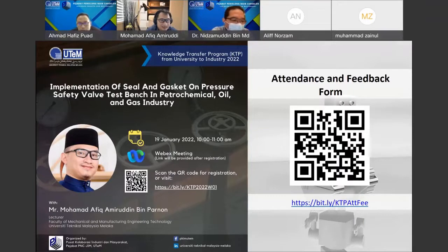Yes. The backup ring, because they have a backup ring, and then the O-ring in the middle, and then for the internal diameter they have another backup ring. So should it be the same material or a different material? No, the backup ring is steel. The backup ring is steel? Steel, okay. Yes. Only the softer material is the O-ring. But the backup ring is steel, the hardest one.